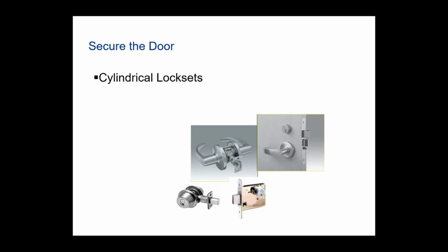The name is very easy to figure out why they're called cylindrical locks. It's because they use a cylinder to be able to connect the two pieces together. There's different grades of cylindrical locks, whether it be grade 1, and we talked about that earlier. Based on the cycle test, they are given grade 1, grade 2, and this isn't mentioned here, but also grade 3. Grade 3 is going to be very, very economical line of hardware.